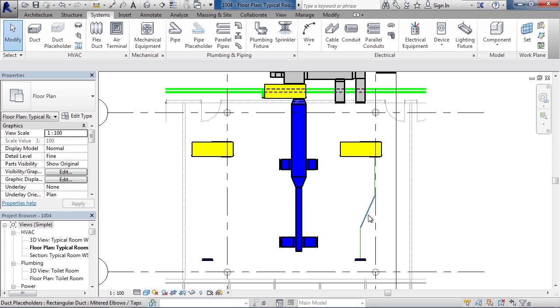This green line actually represents a placeholder duct or duct placeholder system. Basically, it's the same thing, except it's only being represented by a single line. Typically, it's used in conceptual design if you're just conceptually laying out that duct arrangement or that duct line. It still does connect to your diffusers and your air handling units. But the difference is it doesn't have justification values, simply because it's just a line.